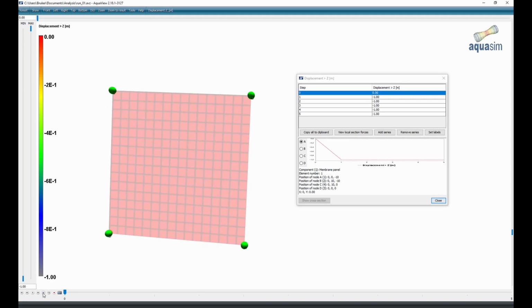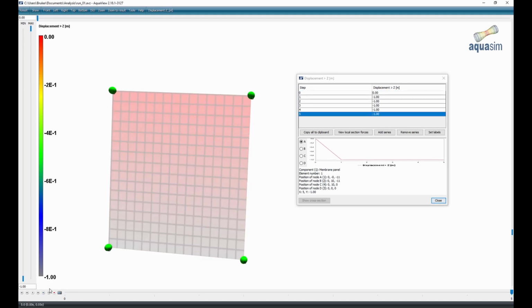Now that we see there is a logical connection between the input and results, we are ready to apply the nonlinear data table to a physical model. It should be noted that introducing nonlinear material properties will influence convergence of the analysis. Usually, it is more challenging to achieve convergence the more nonlinear the material behavior is.